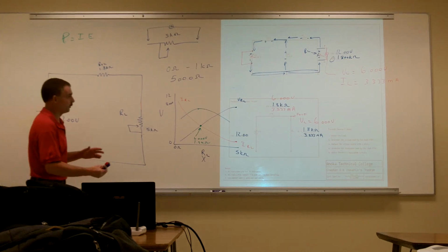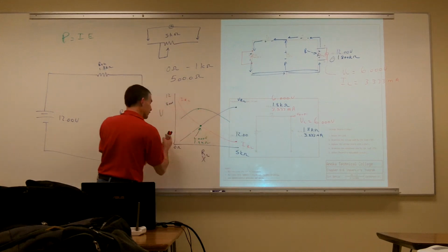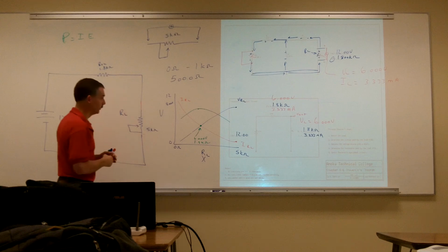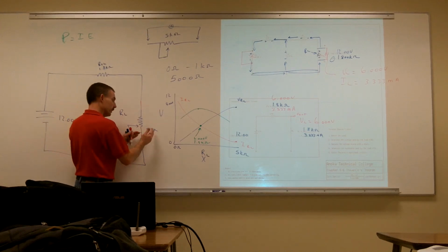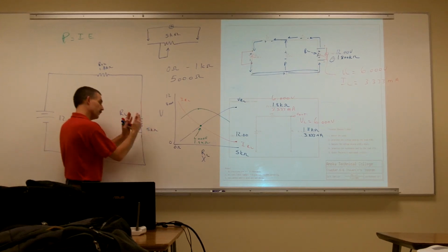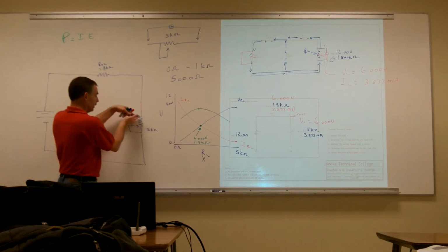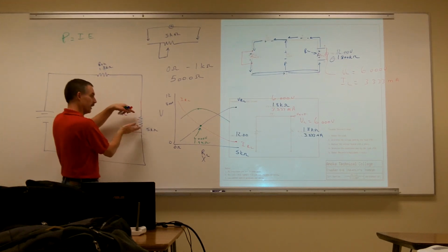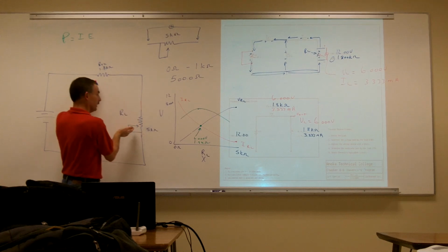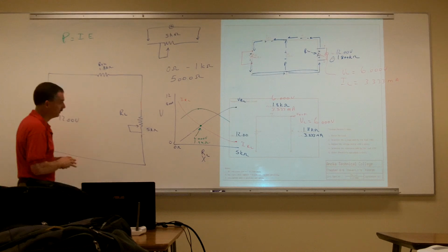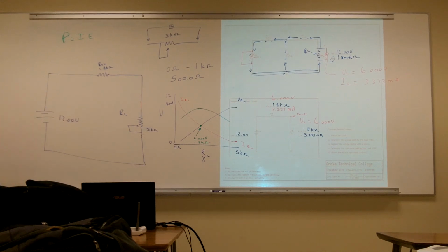So again, sometimes we have to work our way backwards. A lot of times we do it this way when we're working with our circuit, when we're working with our labs and stuff like that. But out in the field, though, we always like to start out so that we have the minimum amount of current. That way, as we start decreasing our resistance, if all of a sudden our current starts to go high and we don't want to do any damage to our source, we can go ahead and stop the experiment and just say, oh, something's not quite right here.